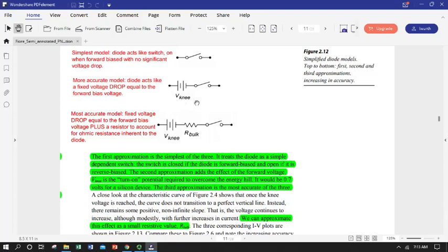That's the forward bias voltage necessary to start conducting that we saw in the current voltage plots. This is also known as V forward bias, or VF in some types of analysis. So we basically have this battery in kind of backwards to the direction that current would flow.